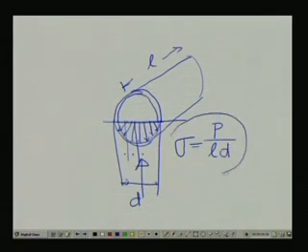So, this becomes a bearing stress in case of the circular hole. You remember, whenever there is a circular hole and we are having a contact of the shaft just described, we always take the area as a length and the projection.